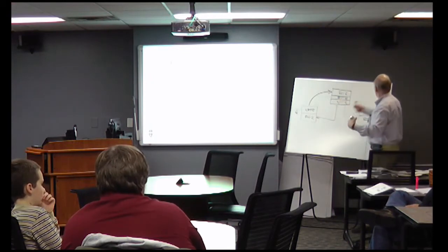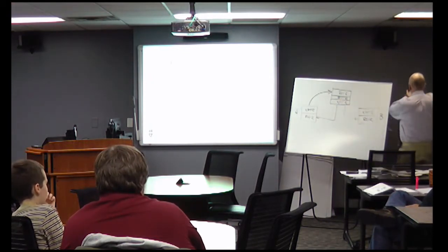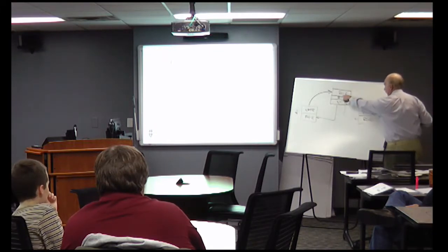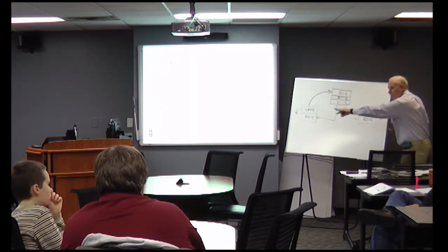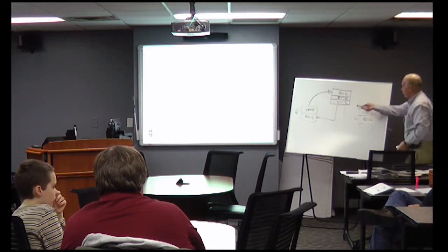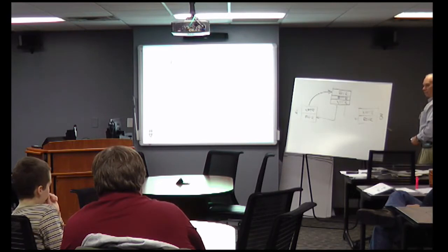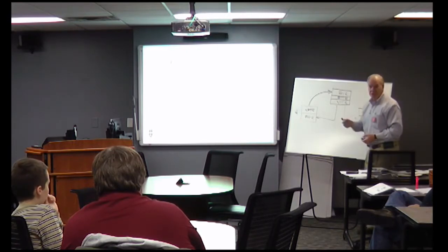So we don't want somebody over here in this geographic community transmitting on a frequency that would activate the repeater over here. Well, the way we do that is that we put a different PL tone on this repeater and that repeater. Think of it as just an access code.